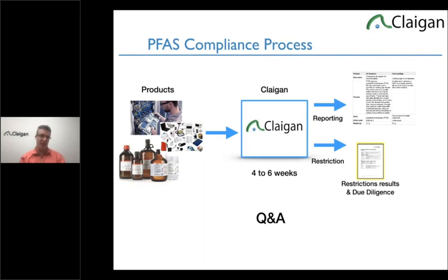PFBS is a flame retardant in polycarbonate. It's also a short-chain relative of PFOS, and it's got a strange use that I don't actually have listed in the uses, as a flame retardant in polycarbonate. It's also REACH SVHC, actually. It's a higher concentration intentional use. It's not restricted right now, but it is actually REACH SVHC. It's a really weird one, PFBS, which is extremely rare.